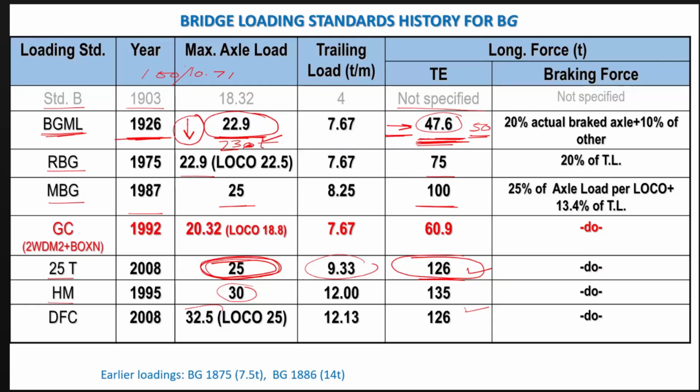I agree with you. That's why I am saying that as far as possible we should go standard. Even then, if there is any site constraint or specific constraint, you can go non-standard. But in that case, first, the drawing has to be preserved. Second, the interaction ratio between the permissible stress and the actual stress should not be very close to 0.99.